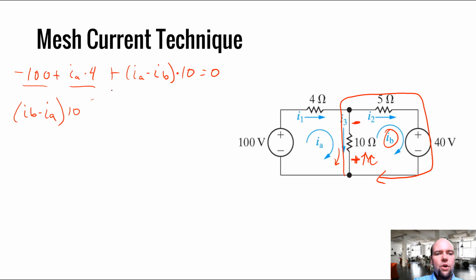So you'll see these two equations are the opposite of each other. Take this equation and multiply it by -1, and you get negative IA plus IB, right? So we got essentially the negative equation, which you'd expect, because in one case we were writing the voltage drop top to bottom, and in the other case we were writing the voltage drop bottom to top. But we got it by thinking about this two different ways. And the way that I think about it in my head is, I desperately want to use V equals IR.